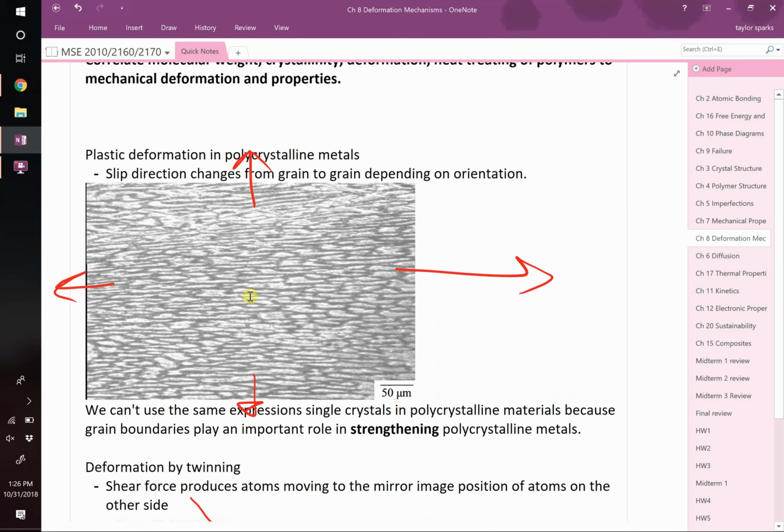If you've ever seen how they make aluminum foil, it's just absurdly thin. The way that they get there, it starts out as a big ingot of aluminum that's about a foot thick actually. Shocking. And what they do is they've got these rollers and they just basically make those a little bit closer together than your block of aluminum is. And they send it through. So it's going to slowly smash your material. And those grains get rolled out. The grains go from being nice round grains to being these pancake grains over time. They just keep on passing it through.